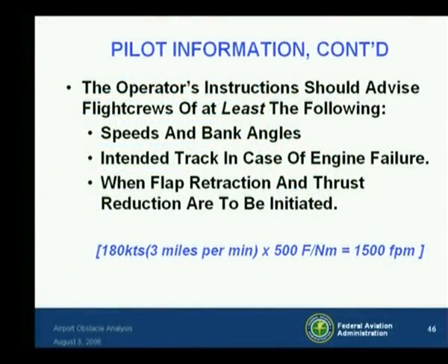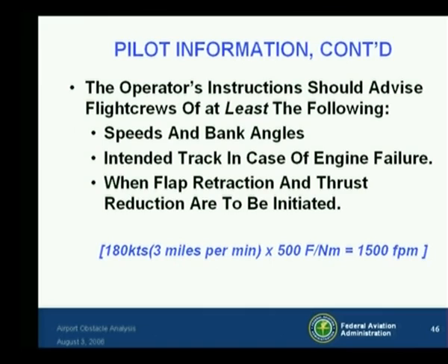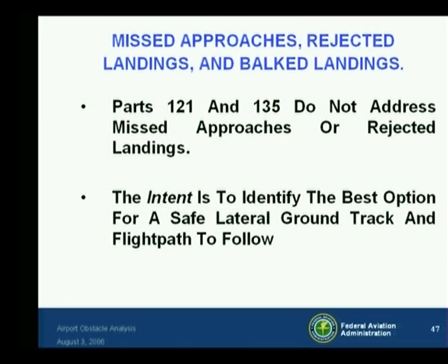Now, this advisory circular addresses some very important concepts that significantly impact EOP procedure development. Namely, that there's a difference in what a missed approach is, and what a rejected landing means, and what a balked landing means. Let's take a quick look. Parts 121 and 135 do not specifically require an obstacle clearance analysis for one engine inoperative missed approaches or rejected landings. It's the classic missing rule.